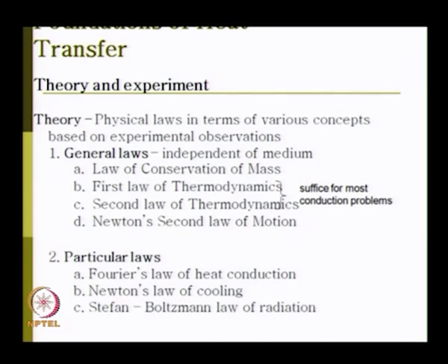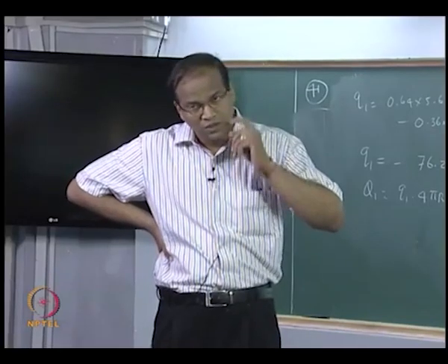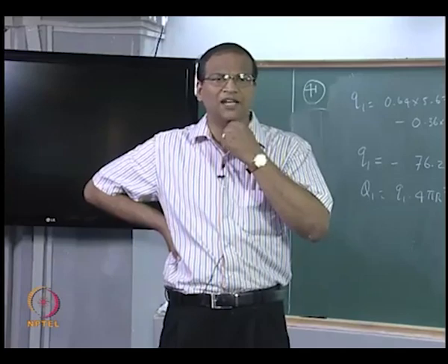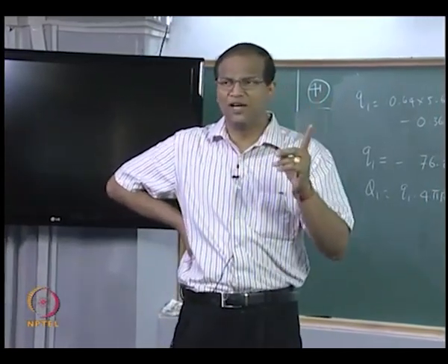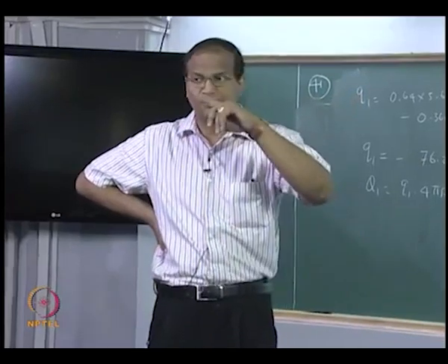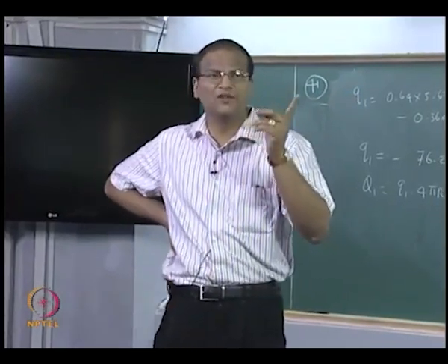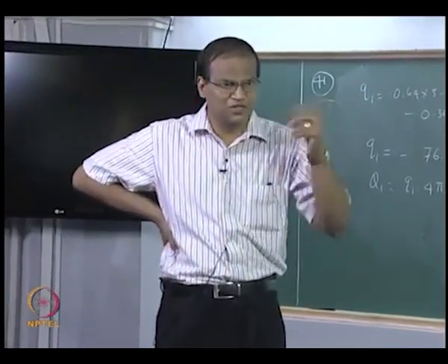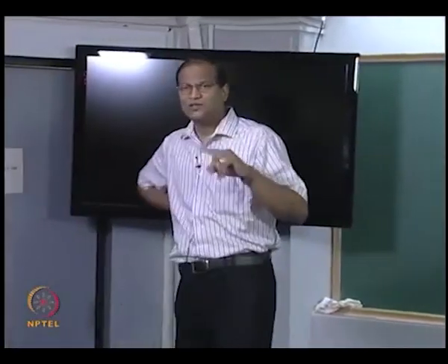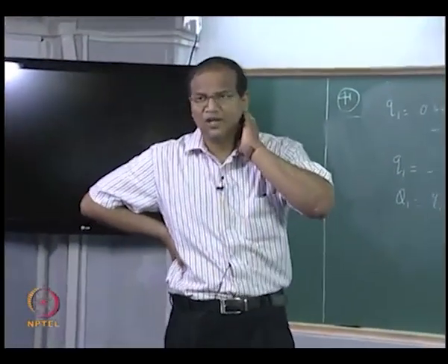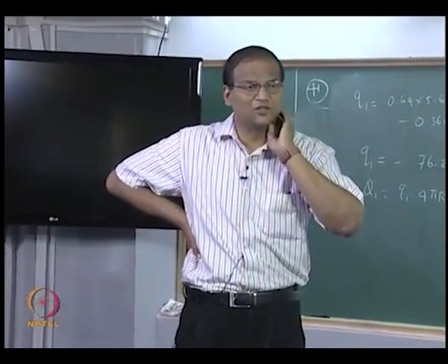The heat source which causes the conduction or the body is moving, but no convection. The re-entry vehicle or a space application, whatever, so the body is moving, there is a velocity, and then you have got a convective boundary condition. The boundary condition will come because of mv squared by 2. Mv squared by 2 is stopped and is converted to enthalpy on the surface. So in these applications the body is moving. Can you give me some applications where the source is moving?